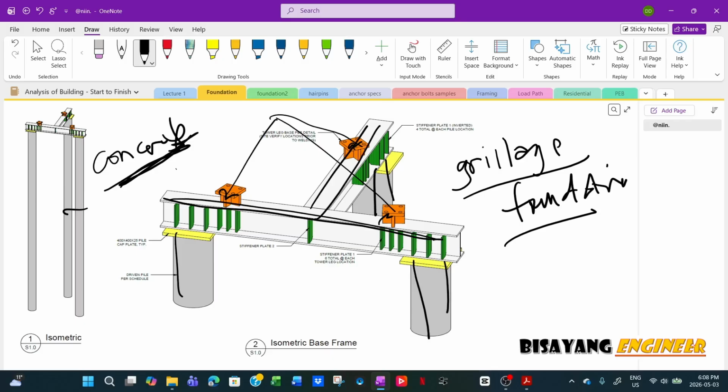Instead of the usual, for example, back home, for a tower foundation, the most common is you have footing and pilaster on three sides. But here, sometimes it's really remote and it's almost impossible to bring in concrete, so they will just use a pile or driven pile.